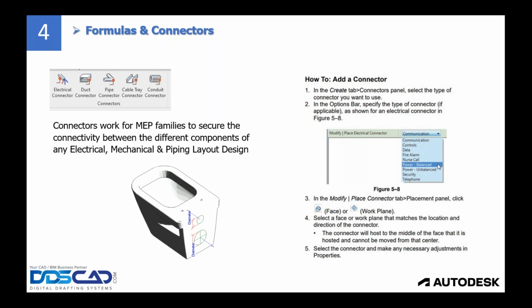And this is a good example of that. I took this information from one of my lavatory, or toilet, families, and you can see here water closet, and there are some connectors very clear here. One is a pipe coming out and another one is a pipe coming in. You can tell this is sanitary coming out from the water closet, and there's a cold water coming here to the water closet to provide service. So those connectors exist in Revit, and they are very powerful.